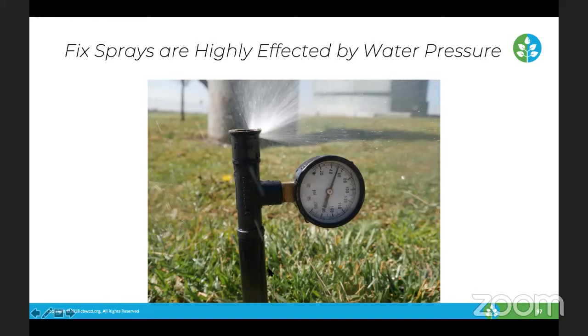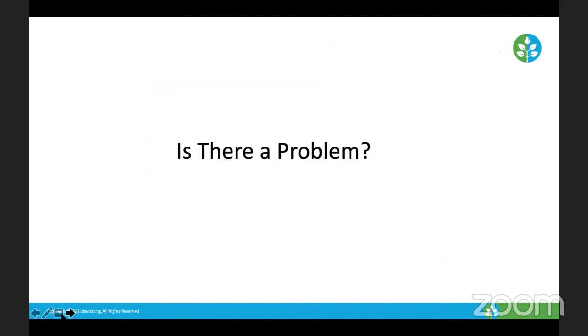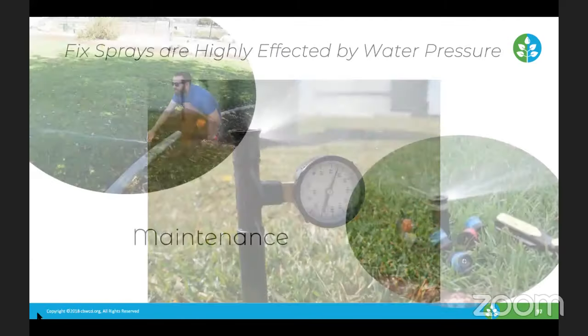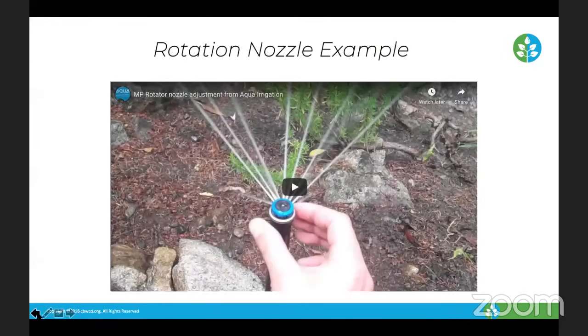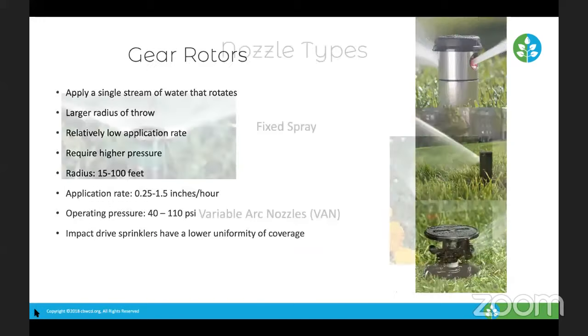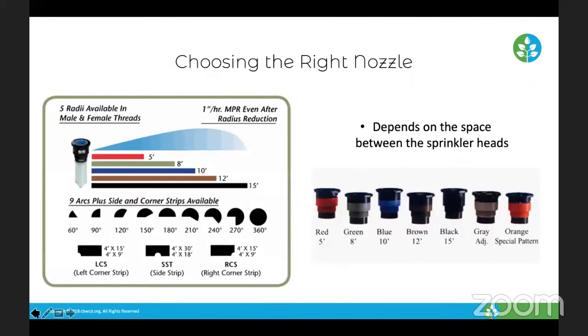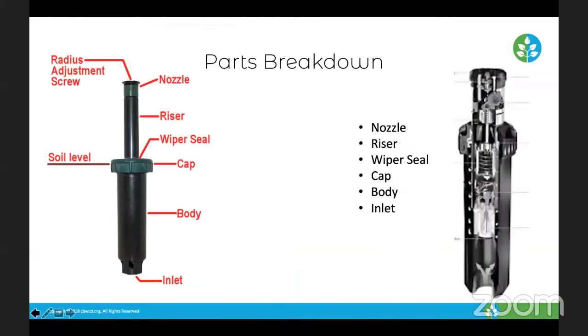So now there's sprinkler bodies. Let me go back so I could show you a sprinkler body really quick. The sprinkler body actually has pressure regulation inside of it. There's a pressure regulator that goes underneath the inlet, and that's going to keep 30 psi after that regulator.